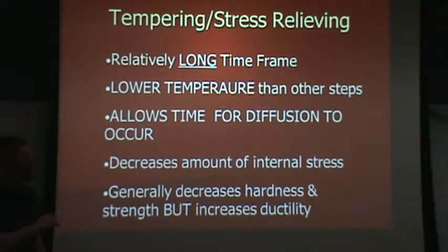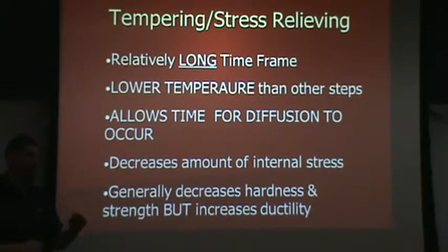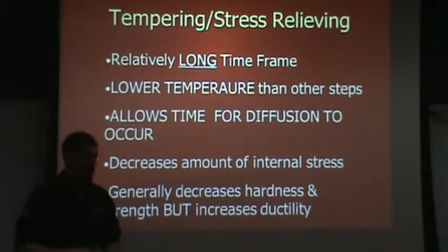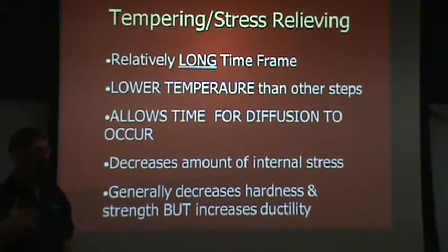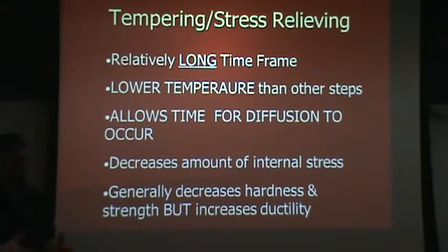If we were able to do a study of microstructure versus tempering temperature and hardness, you'd be able to see how that changes. Something that's tempered at a low temperature, just a few hundred degrees, or maybe not tempered at all, say just in the as-quenched condition, looks very, very different from that same alloy tempered at 1200 or 1300 degrees. At those higher temperatures diffusion can happen faster, so more diffusion happens, and the carbon is leaving the structure. You've got a much softer end result.